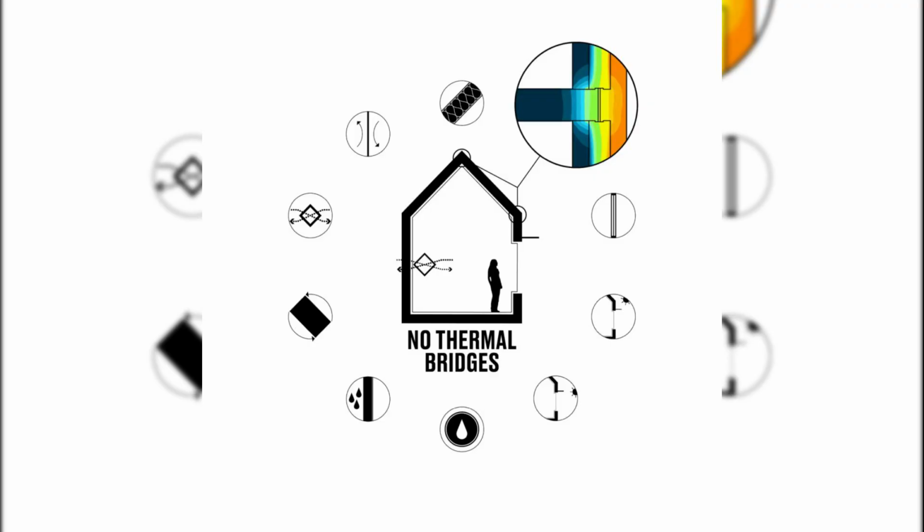The solution is thermal bridge-free design for your home. Introduce thermal breaks, insulative layers, spacers, or separation gaps in structural assemblies. Proper detailing at junctions, walls, floors, roofs, and windows ensures the continuity of the thermal barrier.